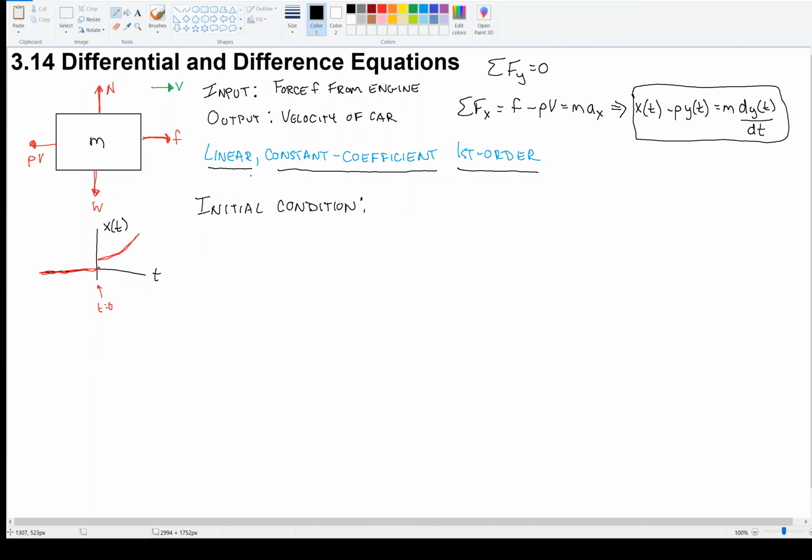Okay, but I guess before that we should just be concrete here. I've got this equation, and now I'm giving you an input, and we can solve this equation for the output y. So that's exactly what we've been doing. We have an LTI system, and I put in an x of t, and I want to know, what do I get out? Right? So this differential equation, a linear constant coefficient differential equation, can characterize the system, just like the impulse response can characterize the system.